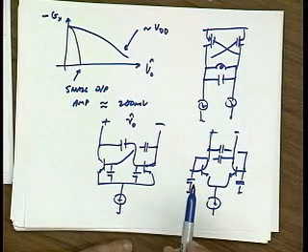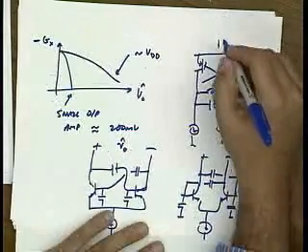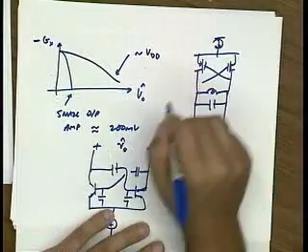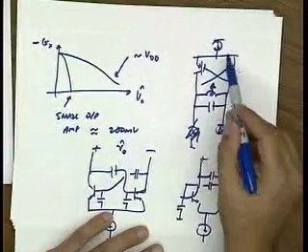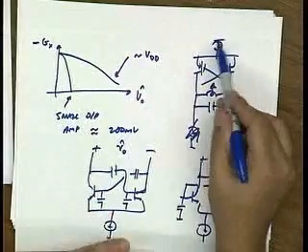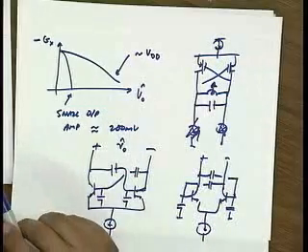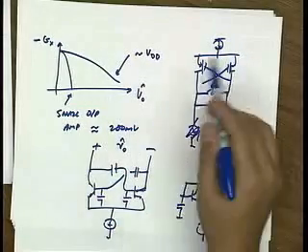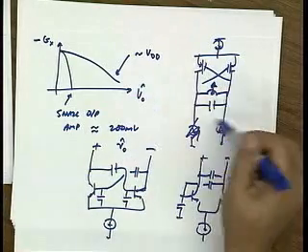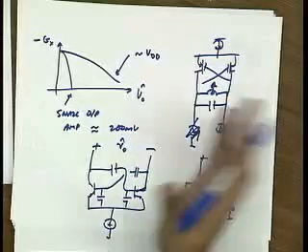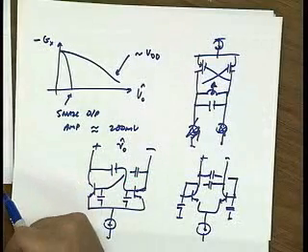You'd much prefer to establish, actually the way you'd do it would be like this. You'd much prefer to establish the bias point through this current source, which is fixed, and it's basically fixed with some reference voltage somewhere in the circuit. And then you can have a very good prediction of what the oscillation amplitude is going to be. If you don't do that, then this self-biases, and you have to make sure that over all corners it self-biases with enough loop gain to oscillate.